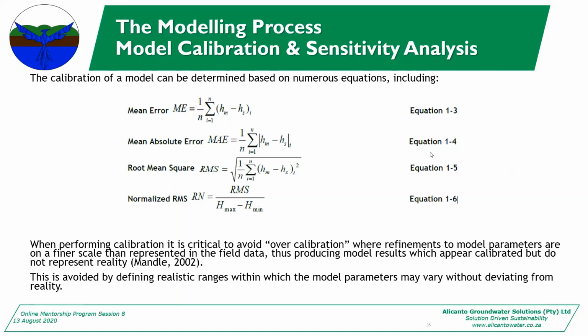Just a comment from my side is this also ties back into your conceptual understanding of the site that you mentioned earlier. You will immediately pick up if there's something wrong with your model. If you have a very solid understanding of your scope or your site, you'll also immediately see if there's an issue. If something doesn't make sense, just hang on and have a look at it, say, wait, the model is telling me I need a recharge of 20%, but I'm sitting in the middle of the Northern Cape where my annual rainfall is 100. How can I have 20% recharge to groundwater?